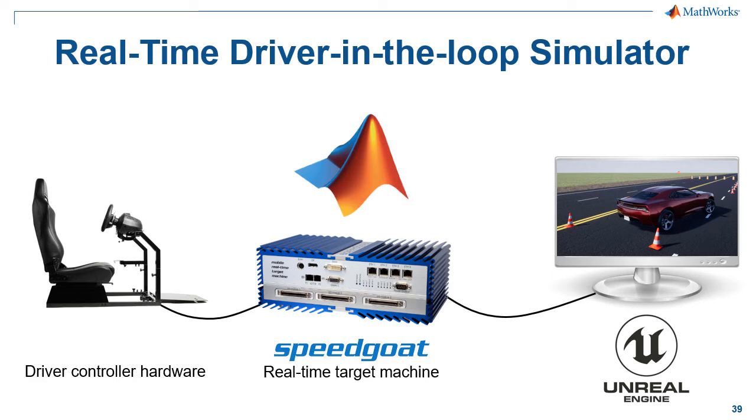For this real-time driver-in-the-loop simulator, we had the plant model, the vehicle, executed on a real-time target machine. In this case, we used a Speedgoat. We had the Unreal Engine running on a computer. This also served as a visual input for the driver, who used a physical controller connected to the Speedgoat real-time machine.